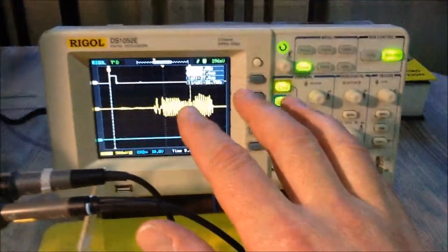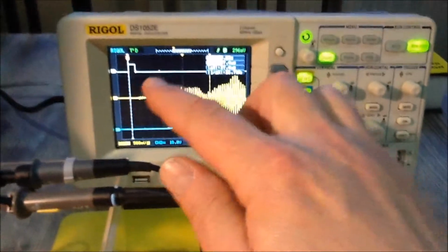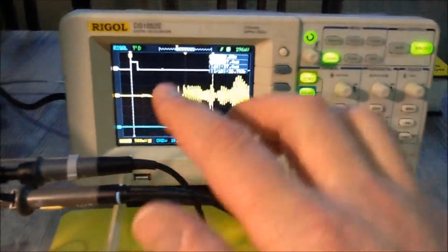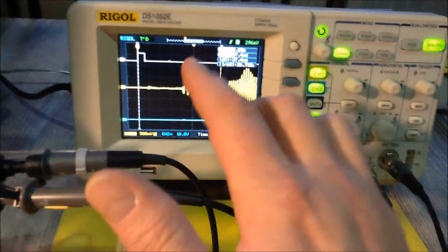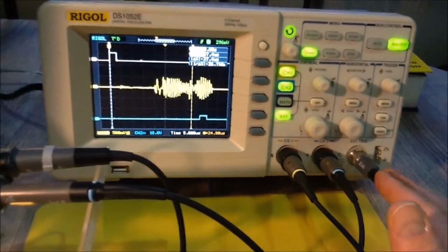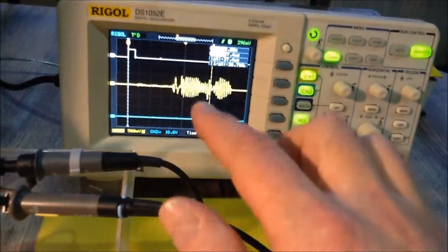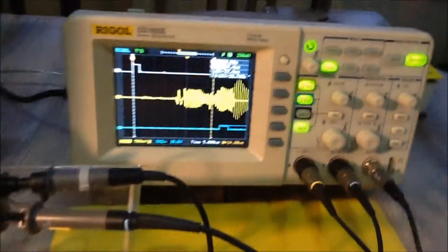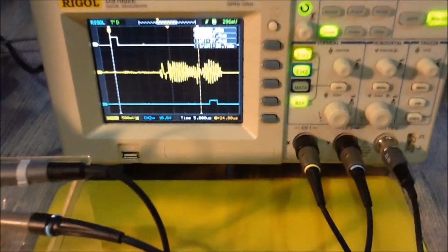Before making this picture, I first connected the A signal to the start. I recorded that data with the reference button here, and then I moved it up so that it's out of the way. From that moment on, I could disconnect the A signal because the scope is triggering on the external signal anyway, so that's the same signal as this one, this rising edge. And then I could reconnect my oscilloscope's A channel to that analog signal coming to and from the sensor.